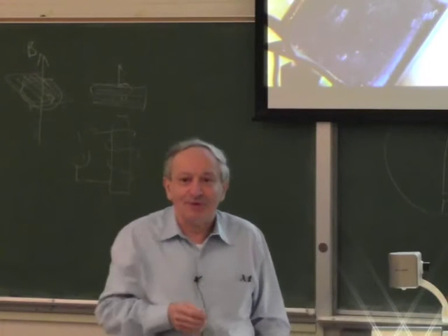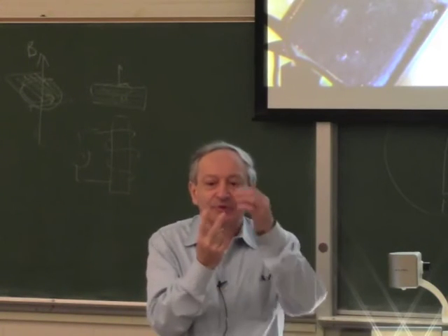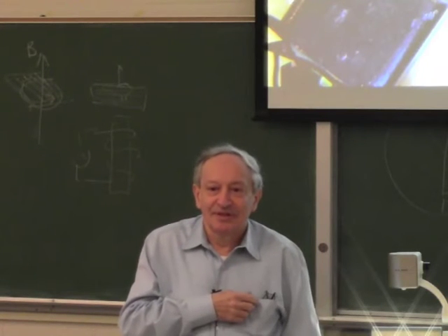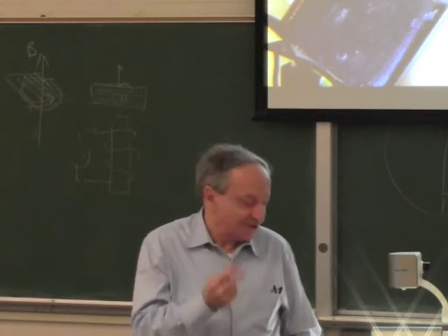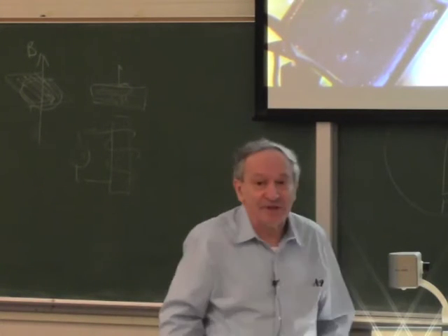What do you think? If you put a copper ring around a magnetic pole, which is split, and you put a copper ring around one half, what happens? Current to be induced. Good. So what happens to the magnetic field? You have two magnetic fields. One is coming out where the ring is, and one is coming out from where there is no ring.